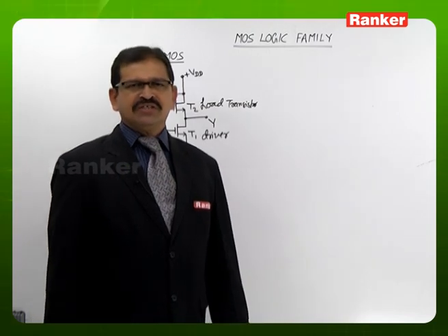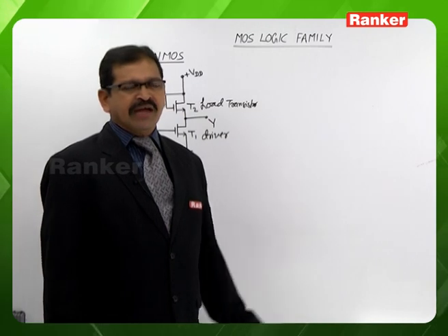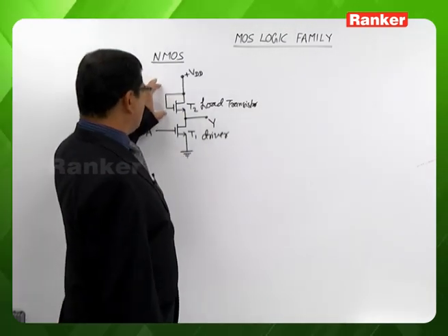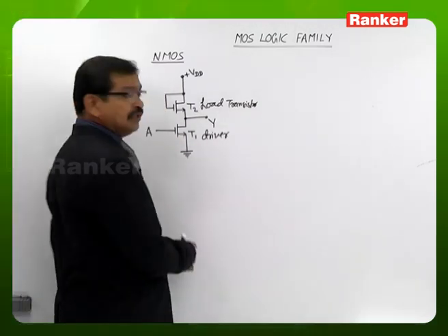Wherever we are in need of a resistor, generally the resistor is implemented, instead of as a passive component, with an active device, the MOSFET itself. So it is the load of the transistor, it is the driver of the transistor. If you look at the operation of this circuit,